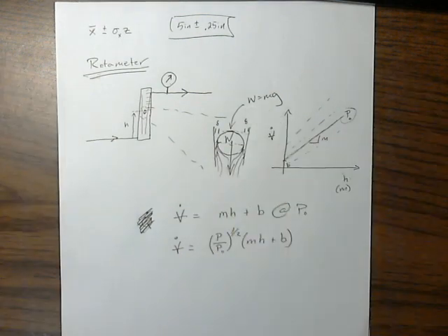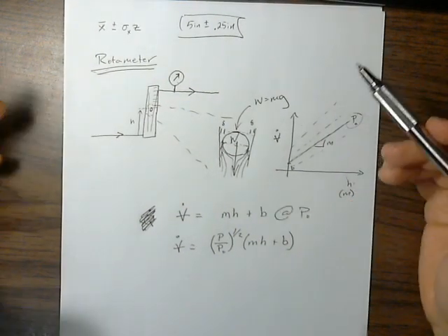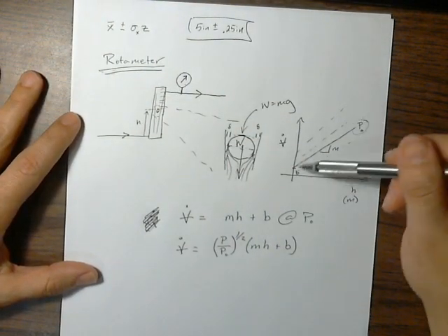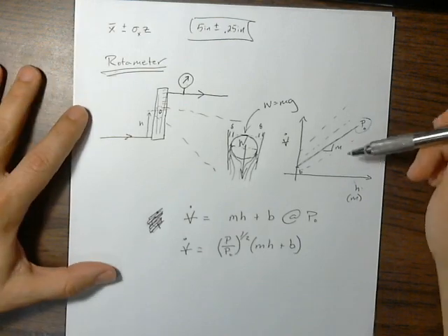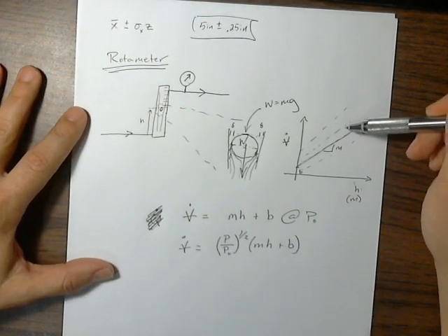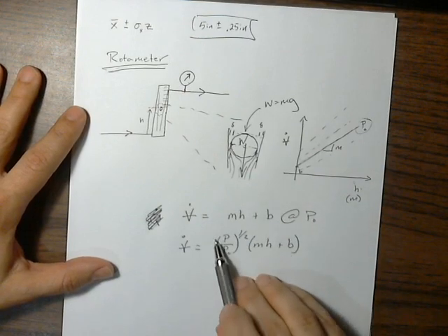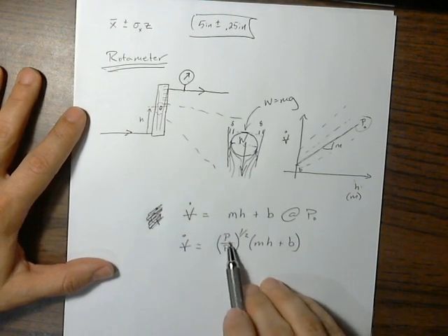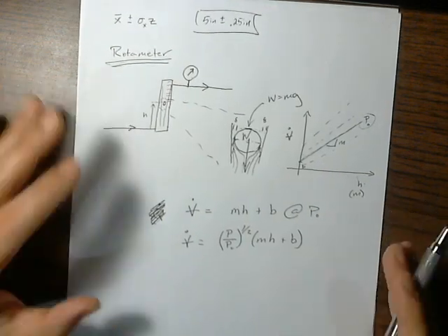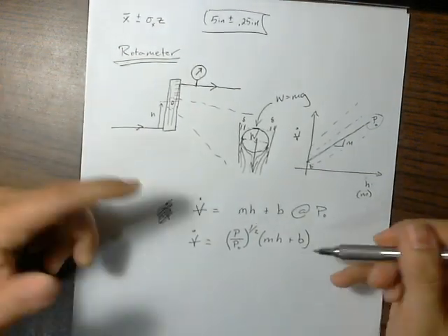So let's say we're doing it in air. Fine. If it's a welding application, it's probably argon, maybe carbon dioxide. It could be a blend, but yeah. So you've done this, you've got it. Great. Well, then we want to adjust the pressure, but I don't want to have to go back and re-measure a calibration. It's okay. We can just adjust the entire calibration by this factor out front, and it'll be pretty darn solid.